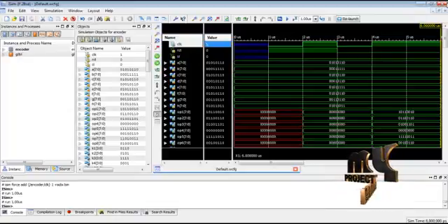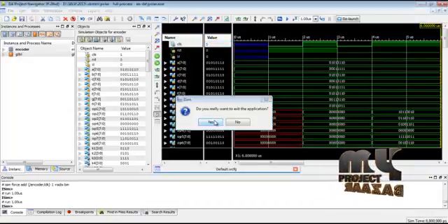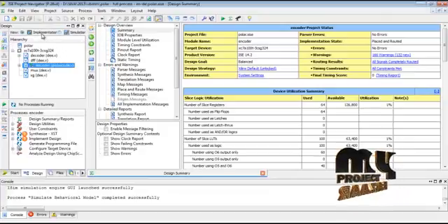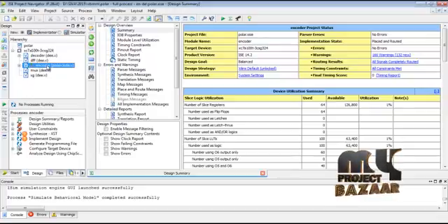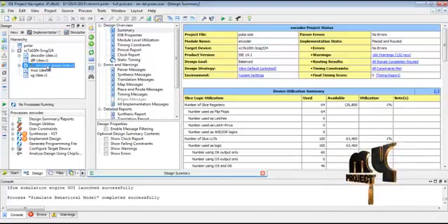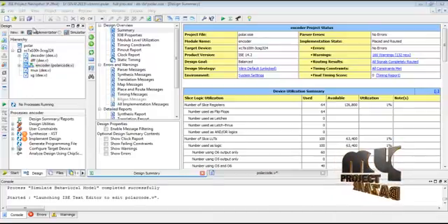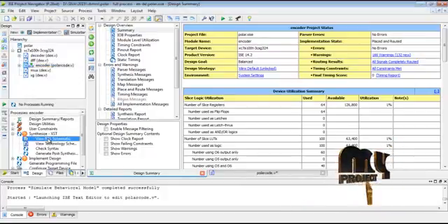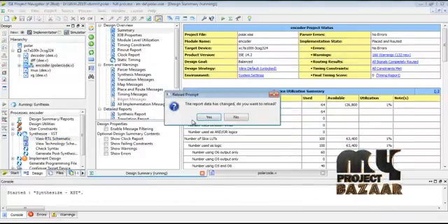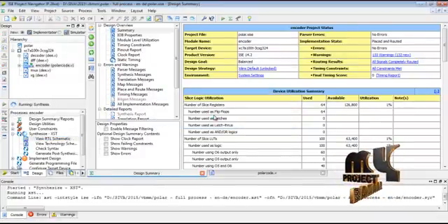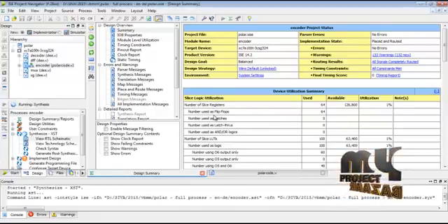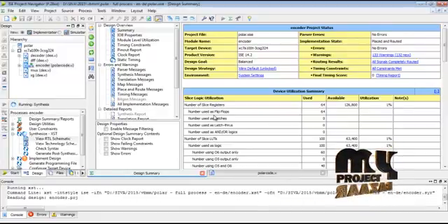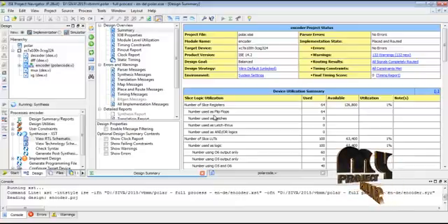This is the simulation output data bits. Then we close the simulation and select the implementation part. In the implementation part we select the encoding architecture. Then we select the implementation process and the encoder function. Then we view the RTL schematic diagrammatic representation. This is the RTL diagram for the overall logical structure present in our programming functions for the polar code based encoding function architecture.